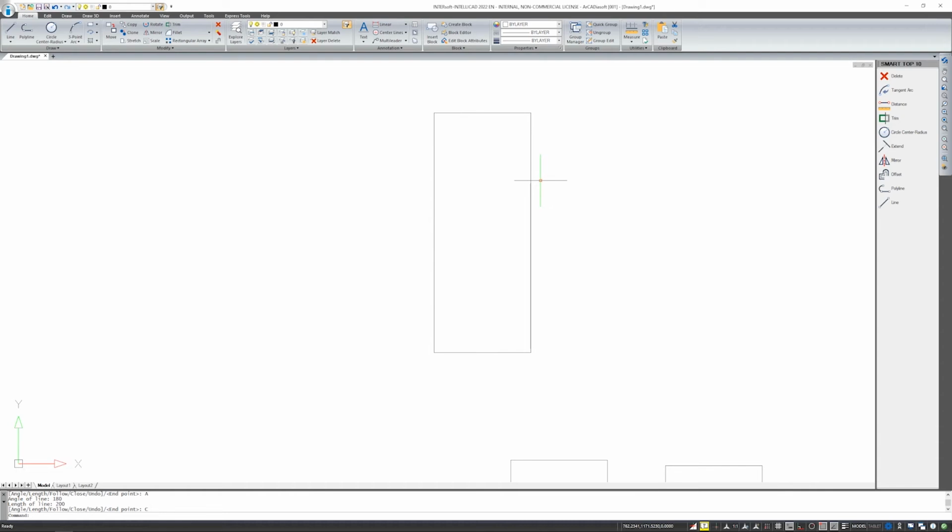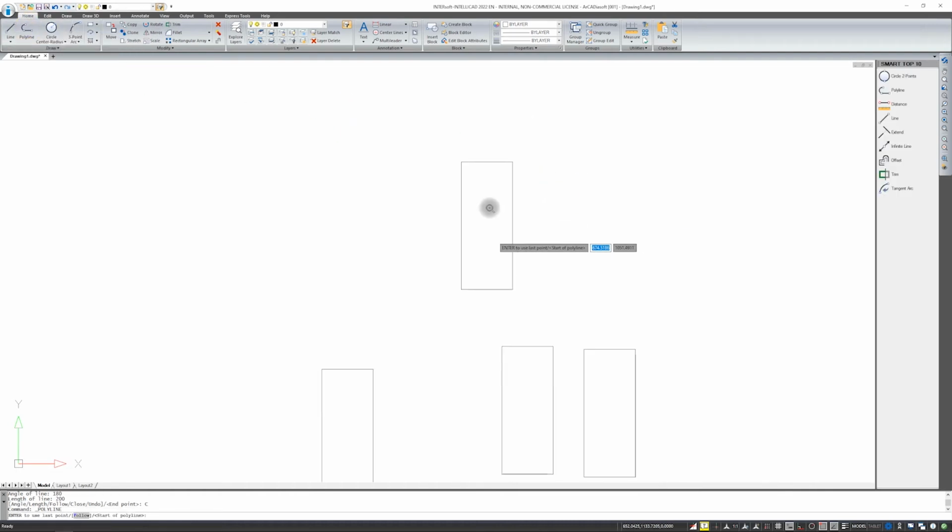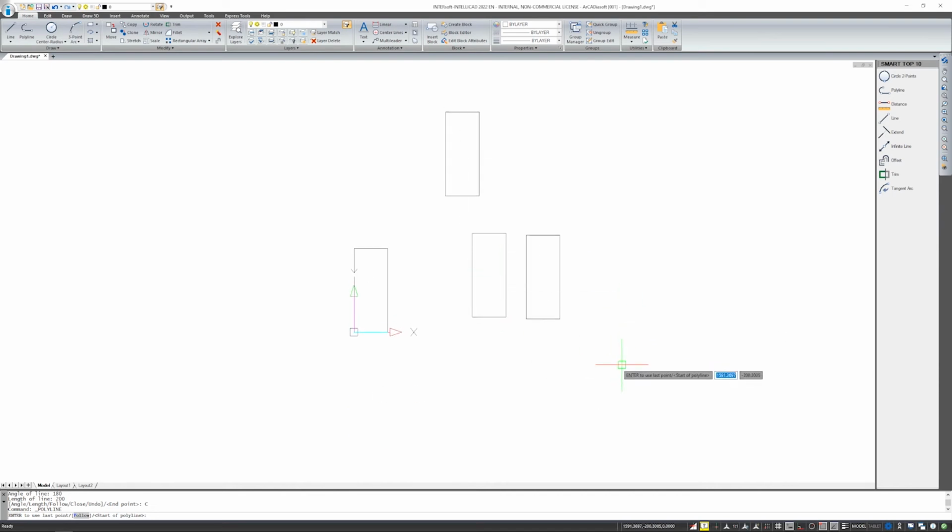Whether it will be a rectangle with a different angle or whether it will be parallelly perpendicular to the screen, it will all depend on your design. There is of course an easier way to draw an element. You can just turn on the Ortho mode and start drawing. This is the button to turn on Ortho here on the status bar at the bottom, or the F8 key if you prefer. And now all you have to do is show the direction, enter the value, and confirm with enter. If you do not turn on the Ortho mode, the program will follow the cursor or the distance you enter, and it will go exactly to the cursor line you point to.